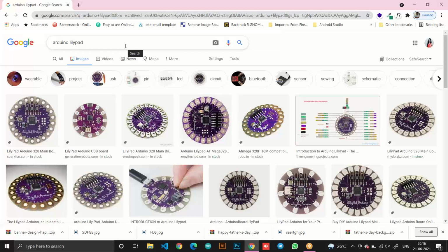Now you have 3 to 4 sensors. You need to integrate those sensors into a board. So how will you integrate that? You can do it with Nano also, but if the coding part is much more complex and heavier, then we switch to the higher version of it, that is Arduino Uno. For basic projects, we always use Arduino Uno.